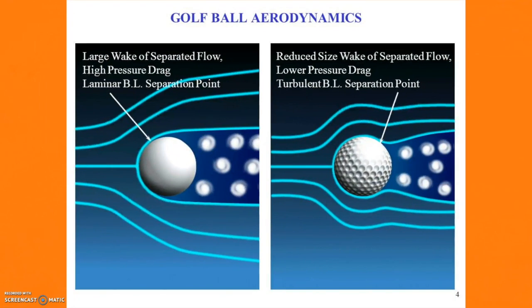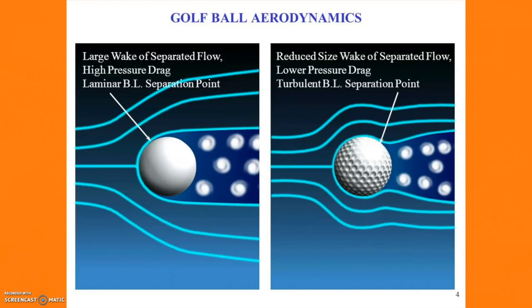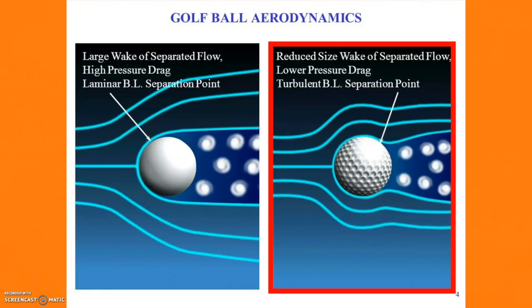What happens when dimples are added to a spherical object is that airflow changes from laminar to turbulent. This turbulence sucks the air into the ball as it pushes past, allowing separation to be delayed. This results in an overall smaller wake region, as a smaller vortex of eddies is created to oppose the movement of the ball, leading to less drag.